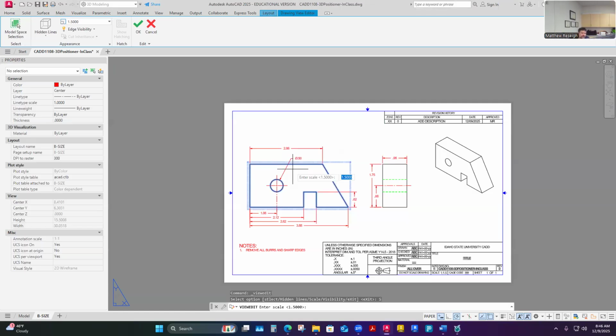That's why title block scales are okay when you only have a single part like this. But when I have multiple parts on a sheet, maybe the scale on my sheet becomes NA because each view is at a different scale. I will notate what those are, especially if they're dimensioned views. If I'm annotating a view, I need to say what scale it is. If I have different scales on a drawing, I can just add a title to my view and put a scale underneath the title.